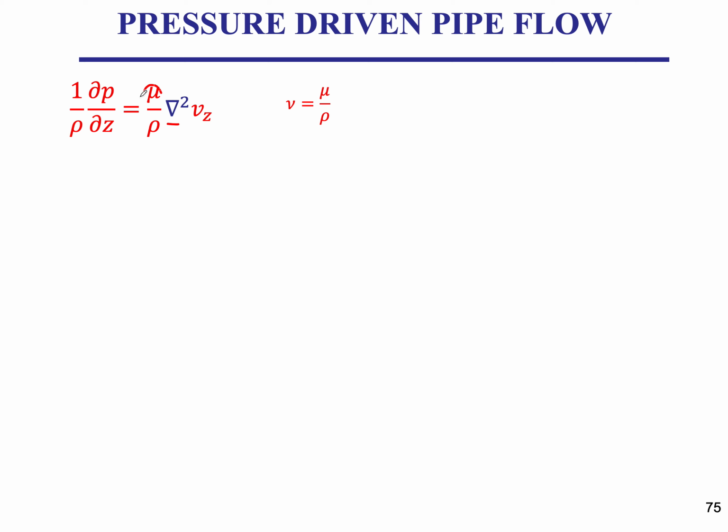And as I said previously, the nu is the kinematic viscosity. It's equal to the dynamic viscosity over density. What are the units of kinematic viscosity? It's meter squared per second. So it's like an area velocity. You throw a stone in a pool, you see those concentric circles going out. This is one example of looking at area velocity. Dynamic viscosity has units of Pascal second. So you want to be able to go back and forth between dynamic and kinematic viscosities through the density rho.